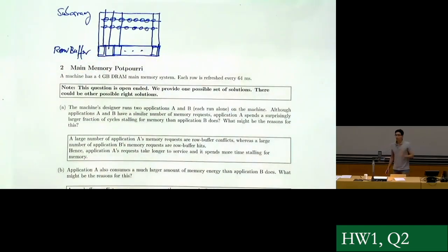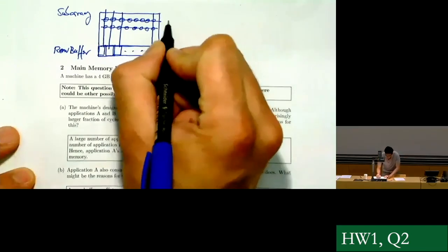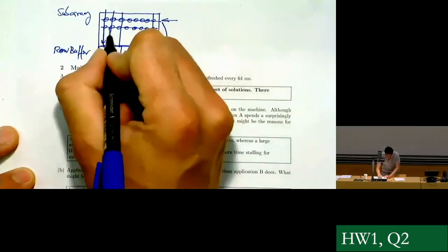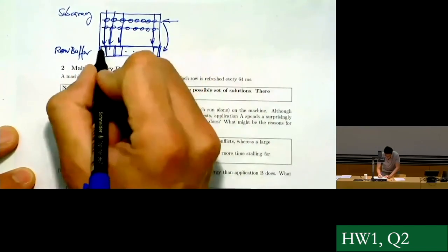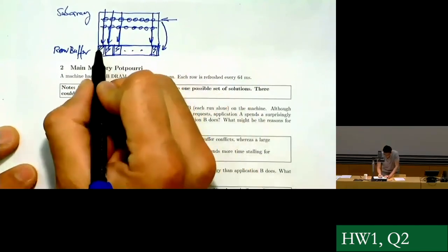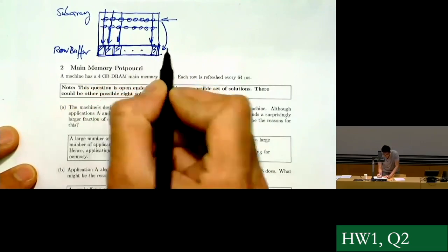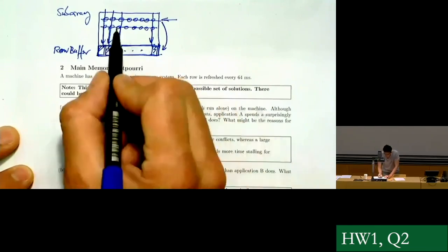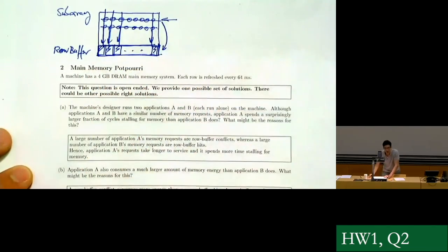Current DRAM memories typically use nowadays one policy that is called the open row policy. This simply means that the first time that you want to access this row, the row is loaded into the sense amplifier. Each of the DRAM cells goes to the corresponding sense amplifier, and this row remains open until someone, maybe the same program, wants to access a different row. That's what is called the open row policy.